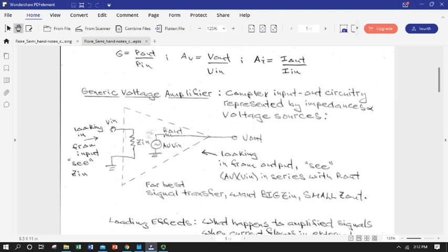So we've got an input signal that can come in, we can apply any input signal, and it's going to see this complex voltage drop, complex impedance, and there's going to be a voltage source somewhere in this circuit that supplies an amplified signal based on our voltage gain, with some voltage drop over an output resistor or an output impedance to our output, which then we'll apply to another circuit, some load, something we're going to do with it.